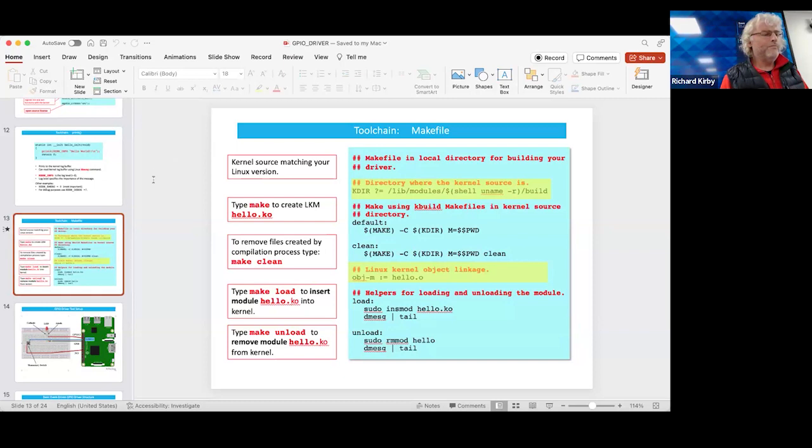How can we push a driver from a plugged-in device? We just set up some special files to point out the driver. So I don't know how that works. For removable hardware, do we have to load it? I don't think so, because you rely on the driver to handle the IRQ. So you need a driver to actually deal with the IRQ. I've never done this, but I'm guessing you might be able to write a little stub driver that handles the IRQ and then sends a signal to user space. And then on that signal, you can perhaps load another driver in.